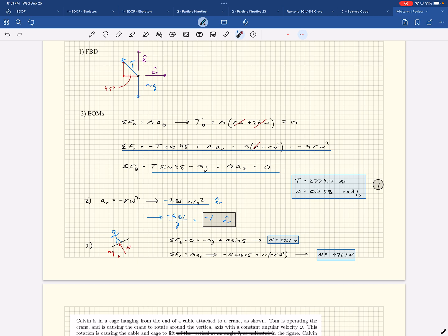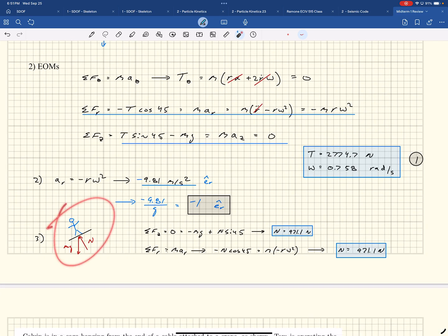Yeah. I like more just, here's my free body diagram, right? I look at it, back to the methodology, I sum my forces. The key to this one was just, hey, let's take a second. We have them lumped together, we solve lumped together, and then you could always do this. Then you can come in and break it up into smaller pieces, and free body diagrams still work. You say what is exactly touching this guy, and what are his accelerations, and that's it. That's all that's acting on him. That's all that it can be, and then this thing comes out of it.